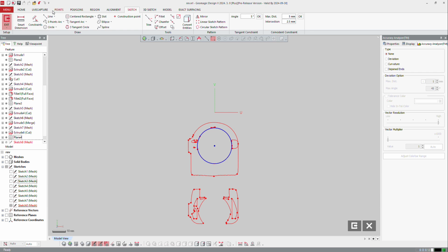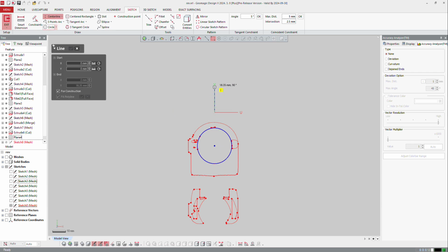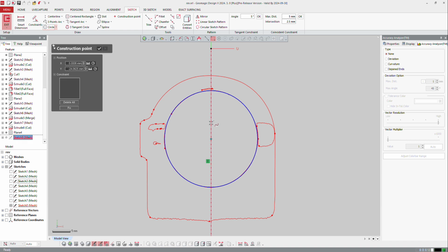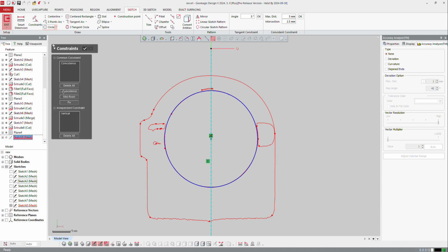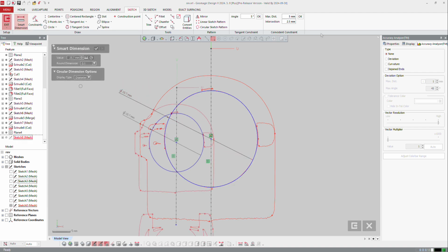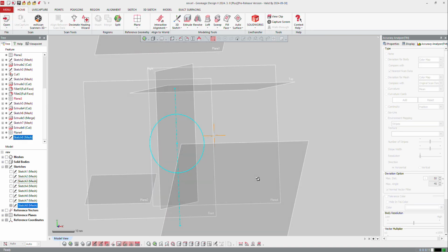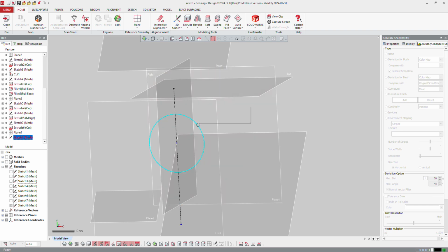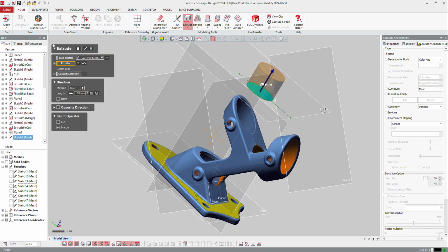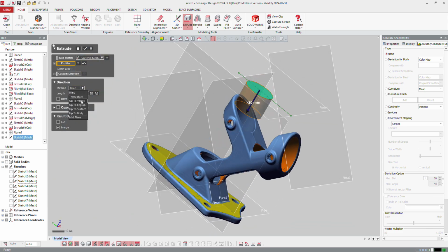OK. If I want to, I can create, as in CAD, a line that goes from that datum to a vertical position, and tell the software that my center, double click on the center, control click on the axis, the information is concentric. Okay, and then smart dimension from here. Then you can exit the sketch. And again, as before, extrude in solid. And of course, display the model, reverse direction, and through all. And of course, cut.